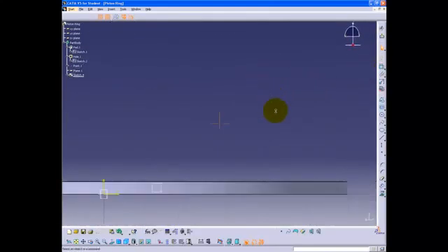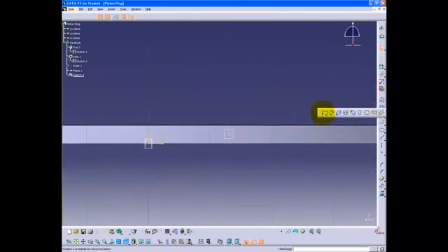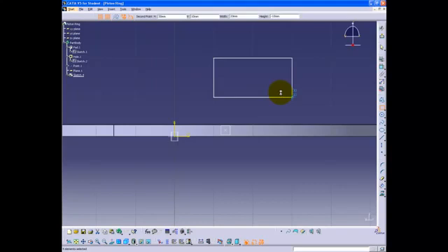Enter the plane created to create the slanted gap. Here, the Rectangle button is used to create the gap. The 1mm gap distance is constrained using the Constraint button. 2B is deleted since the side edges are going to be diagonal.